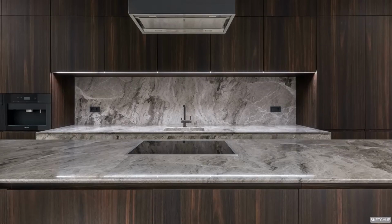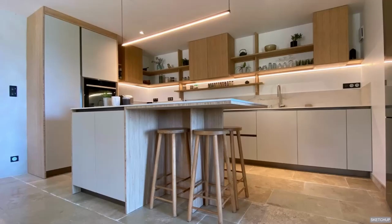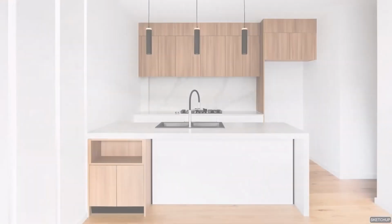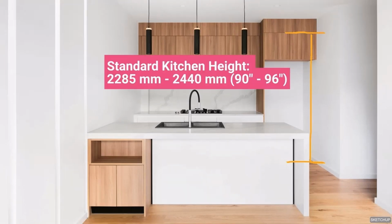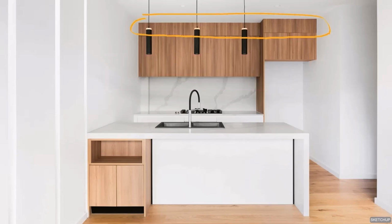Welcome to this lesson where we will dive into the world of kitchen joinery. When crafting your joinery, maximize the vertical space in your kitchen for added storage by incorporating full-height joinery. If budget constraints apply, consider a standard kitchen height ranging between 2,285 to 2,440 mm and complement it with a bulkhead above, creating the illusion of a floor-to-ceiling design.